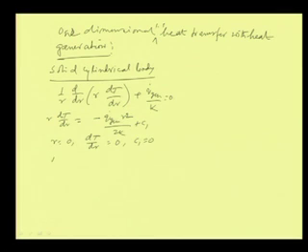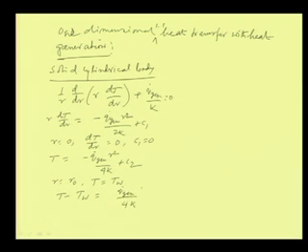And therefore, finally, we can get T is equal to minus q dot gen into r square by 4 k plus C 2, and another condition if we put at r equal to r naught, we have T is equal to T w. So, based on that we will get that T minus T w is equal to q dot gen by 4 k into r naught square into 1 minus r by r naught whole square. So, we are lining up with this equation.